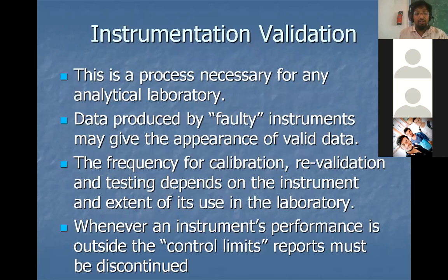Then instrument validation is very, very important. You will have a complete validation subject and complete validation chapters when you come to PG level, master's level. Equipment validation will be there, cleaning validation will be there, process validation will be there, manufacturing validation will be there. So this is the process necessary for any analytical laboratory validation. Data produced by faulty instruments may give the appearance of valid data. So the frequency for calibration, revalidation, and testing depends on the instrument and the extent of its use in the laboratory.